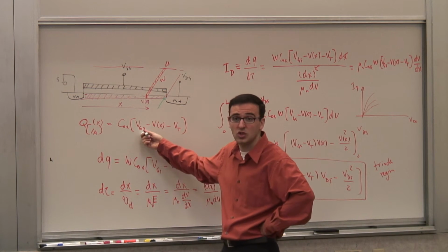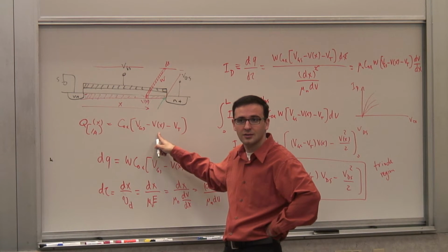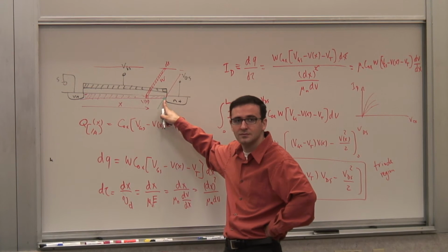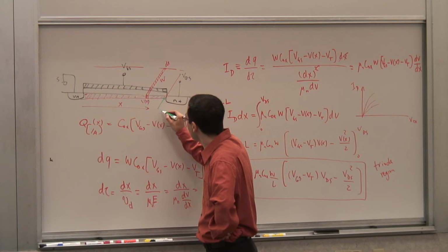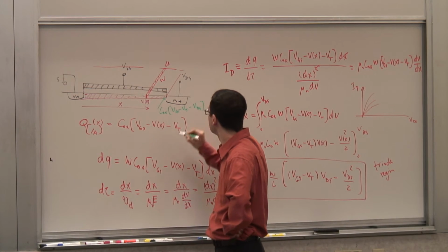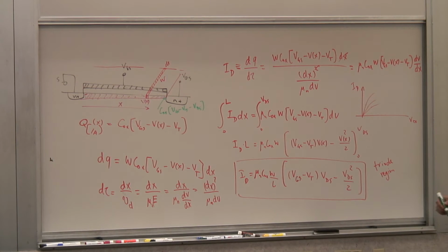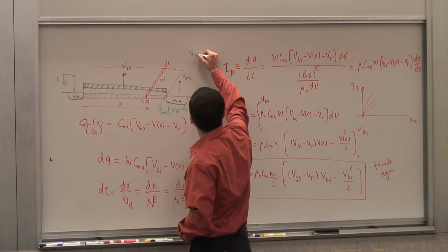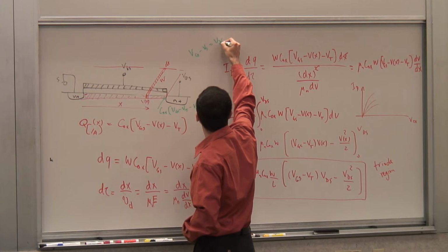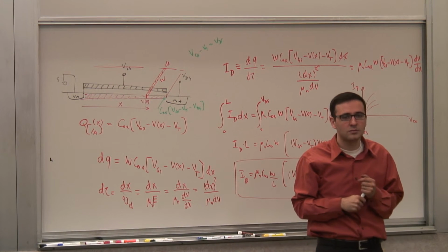Well, this expression was general, right? So we can evaluate this expression for Vx equal to what? At this point, what is Vx? VDS, right? Exactly. So the charge density at that point is simply Cox (VGS minus VT minus VDS). That's the surface charge density, the inversion charge density. So what happens if my VDS is equal to VGS minus VT? There's no inversion charge, right?